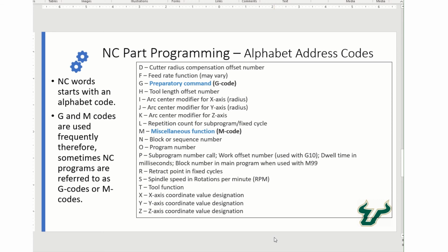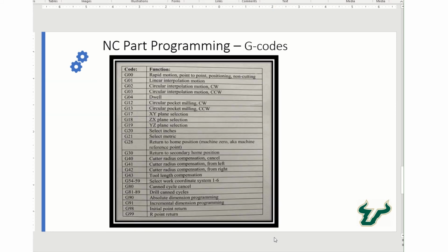Obviously, when you're making a solid model, the program is going to write the codes, automatically generated, and then you can feed that into the CNC machine. But there are always some sort of adjustments that you need to do, and you can't just simply take the code generated by the CAD model and feed it into the CNC machine. There are always some adjustments which are required when you're trying to fabricate the part.